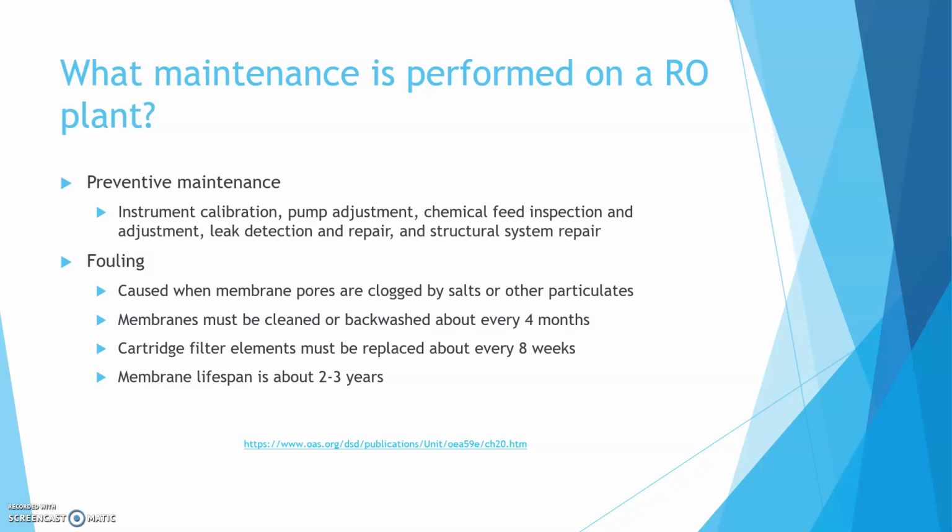Fouling is caused when membrane pores are clogged by salt or other particulates. Membranes must be cleaned or backwashed about every 4 months. Cartridge filter elements must be replaced about every 8 weeks. The membrane lifespan is about 2 to 3 years. And again, the lifespan of the membrane depends upon the nature of the salt content and the quantity.